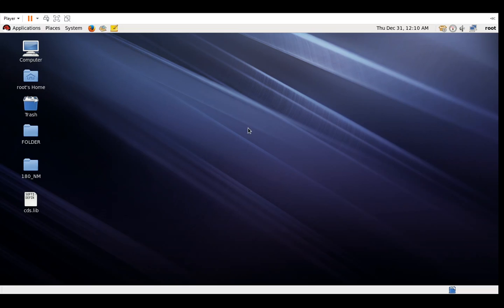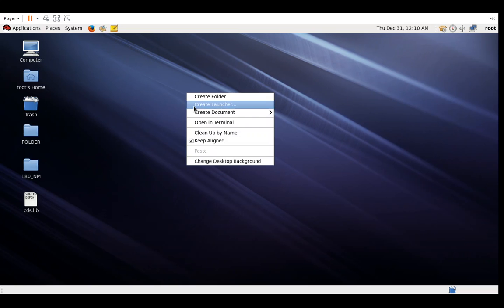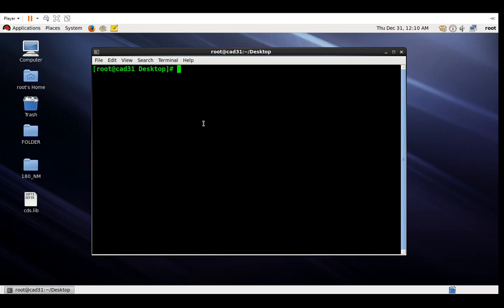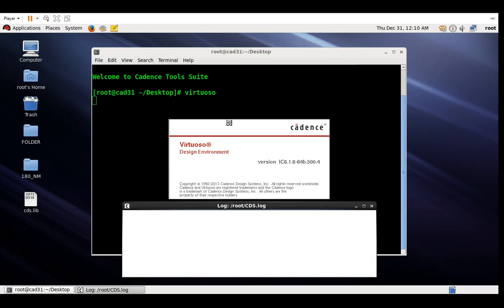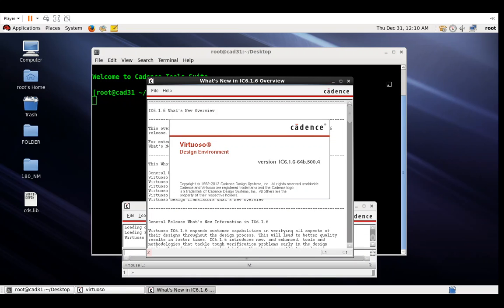So we will just see a sample transient simulation for a two input gate. Okay, so csh, source, home, CAD, cshrc, and start with virtuoso. We are going to do a simple transient simulation, and we are going to calculate the propagation delay from the waveforms.